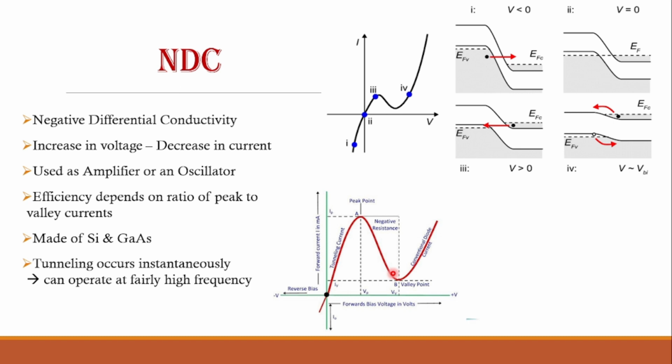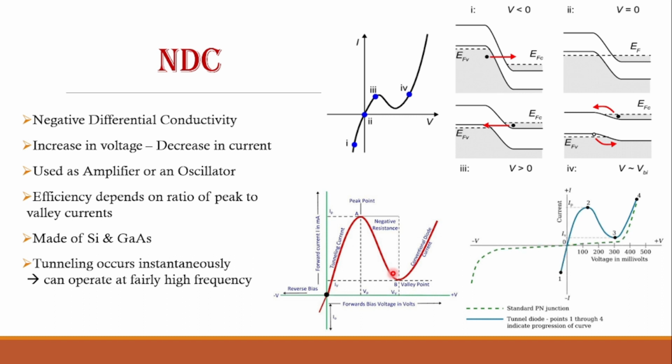And if we want to compare this tunnel diode with the normal conventional diode, the nature of IV characteristics is like this. Here we can observe that for a conventional diode, there is forward current after the knee voltage. Then in reverse bias condition, a very low amount of current is going to flow even for high values of voltage, and finally we can observe there is a breakdown.